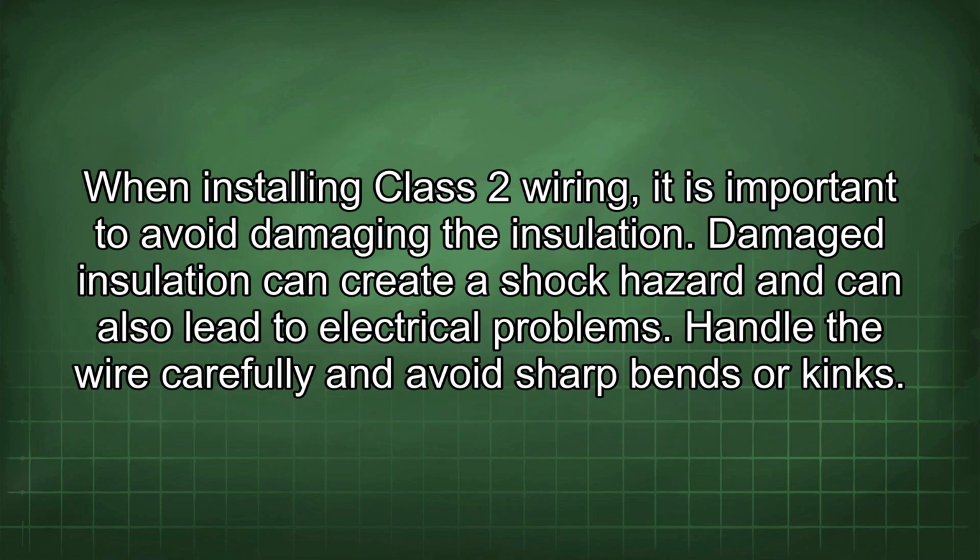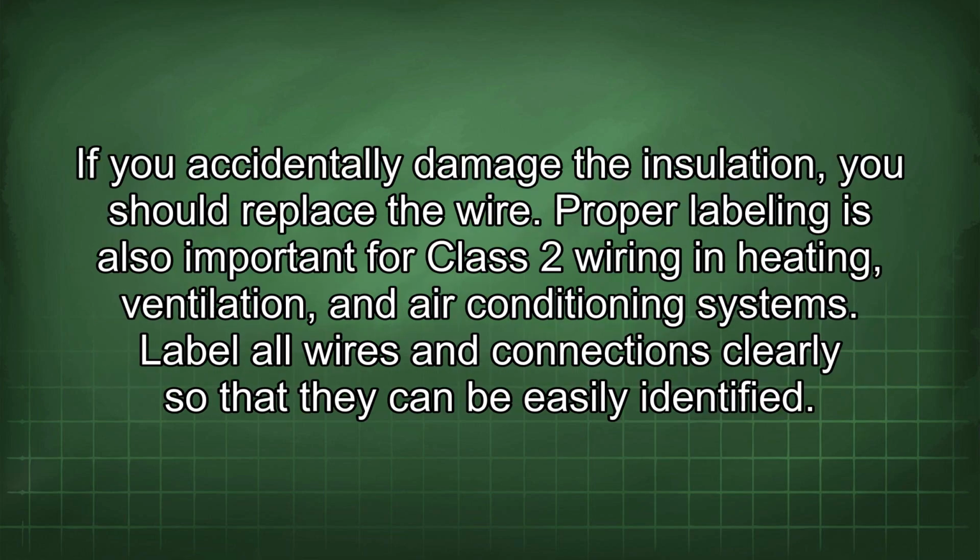When installing Class 2 wiring, it is important to avoid damaging the insulation. Damaged insulation can create a shock hazard and can also lead to electrical problems. Handle the wire carefully and avoid sharp bends or kinks. If you accidentally damage the insulation, you should replace the wire.